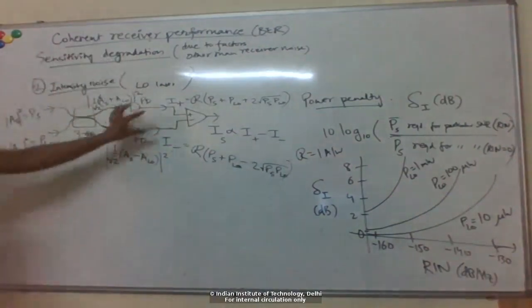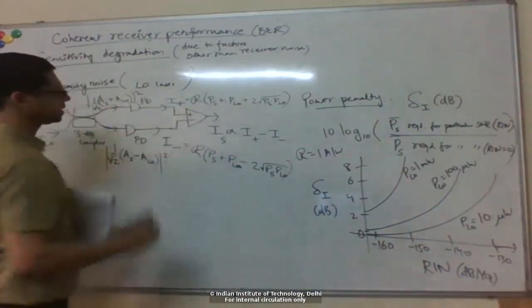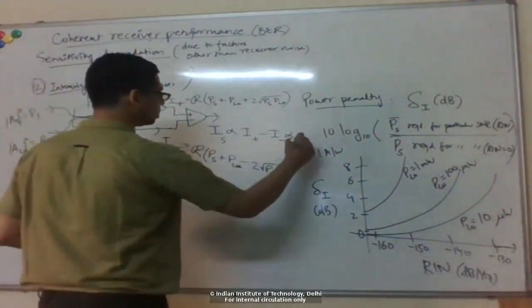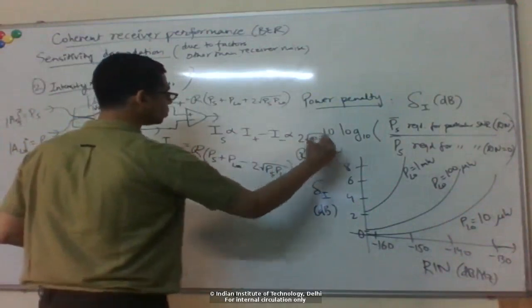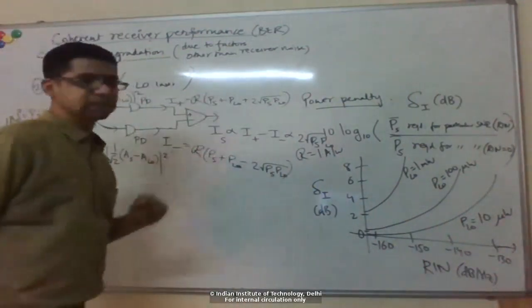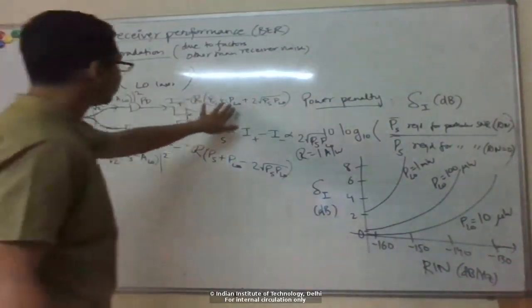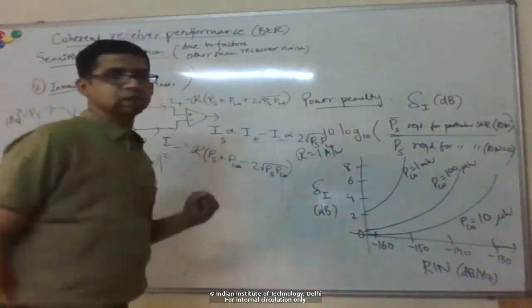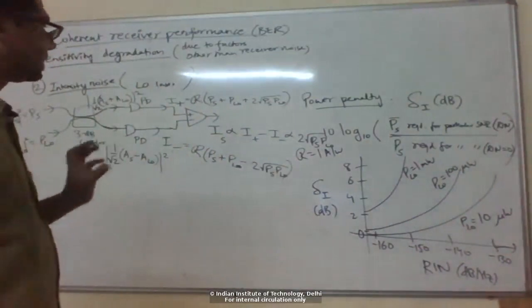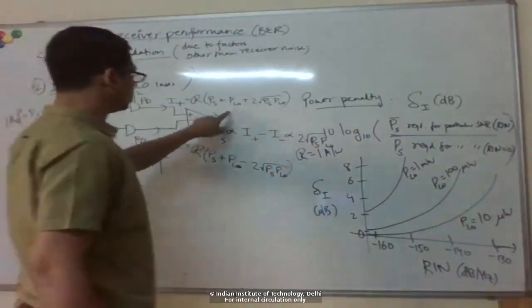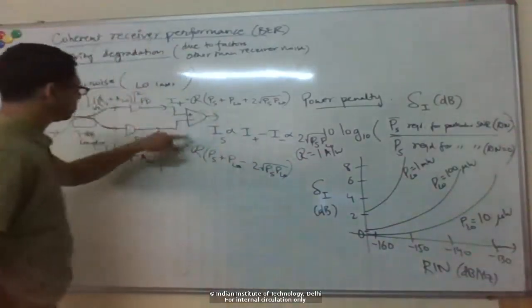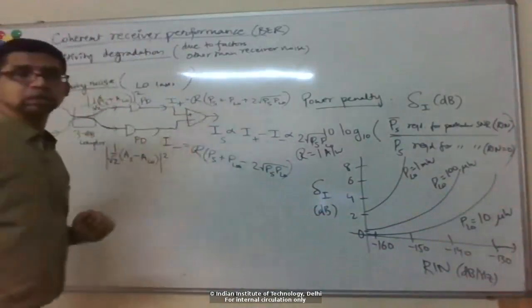Okay. And now when I take the difference, you can see that the DC terms will actually cancel out, right? And I'll get something which is proportional to just the cross term. So firstly, one advantage that you directly get is you directly cancel out the DC term, right? Because this DC term can actually be very large because of the PLO, right? Rejecting this DC term otherwise requires a DC block or an AC coupled detector, right? So to reject this DC is also important and not so straightforward. But in this case, you can see that the DC is already rejected.